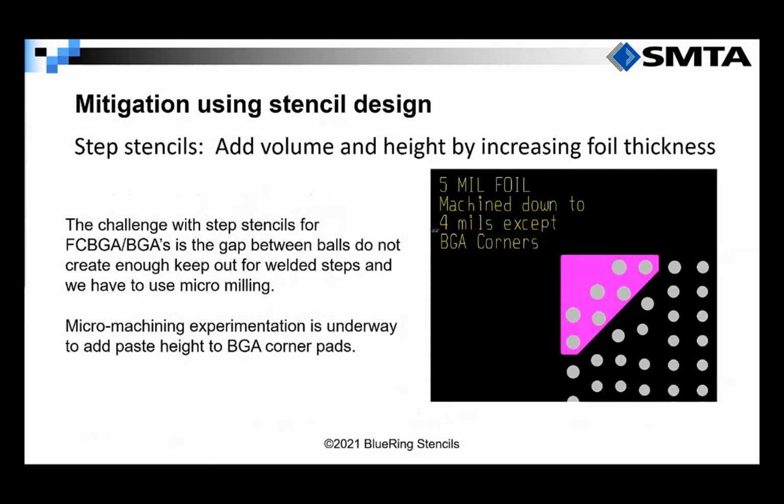So let's get back to our head and pillow topic. Let me take what we just went over and apply it here. Again, if we can eliminate the gap created when this dynamic warpage occurs during the reflow, we may be able to prevent head and pillow defects. Instead of, or in addition to overprinting the corner pads, we could have a step-up area, and this would allow us to create additional paste height and volume and not rely solely on paste height increase from overprint.